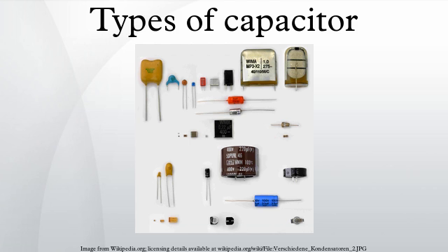The large capacitance per unit volume of electrolytic capacitors makes them valuable in relatively high current and low frequency electrical circuits. For example, in power supply filters for decoupling unwanted AC components from DC power connections, or as coupling capacitors in audio amplifiers, for passing or bypassing low-frequency signals and storing large amounts of energy.